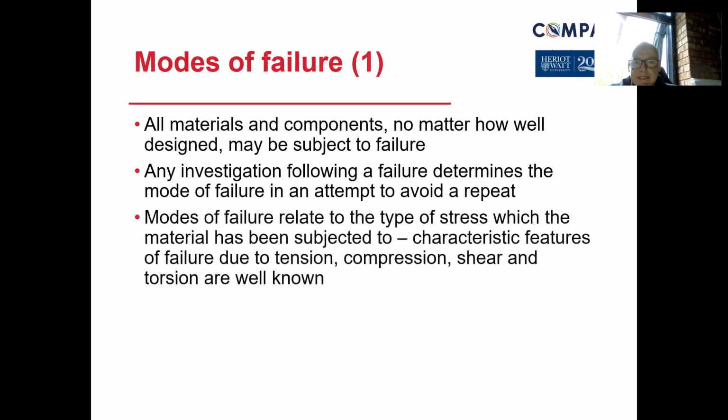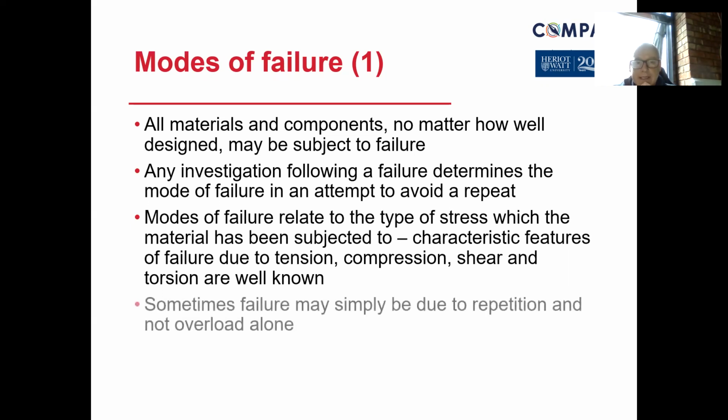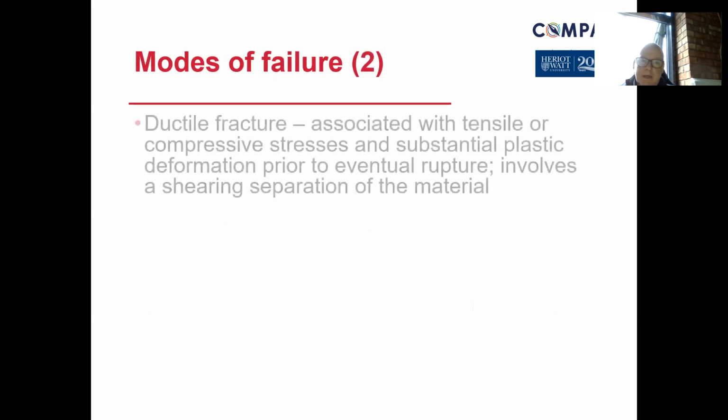Modes of failure relate to the type of stress which the material has been subjected to. So there's that in the thought process, thinking about tension, compression, shear and torsion, as we mentioned earlier. And sometimes failure may simply be due to repetition and not through overload alone. So because of that, we expect failures.